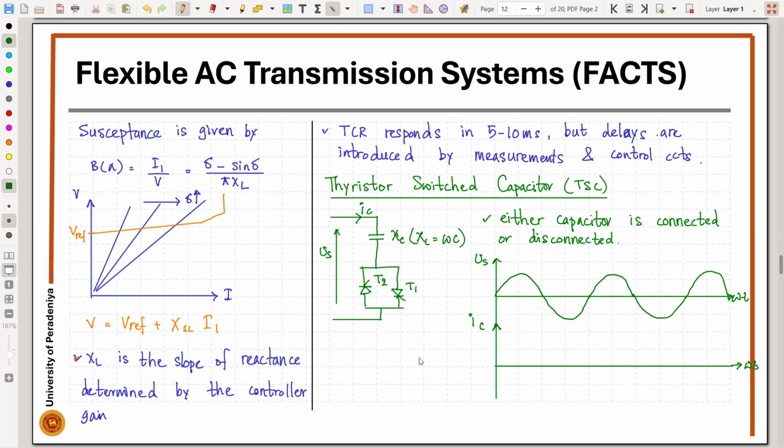usually when we want to turn on the thyristor, what we need to consider is the current flowing through the capacitor, because we cannot control the current through the capacitor. So we have to minimize the capacitor current flow. If the capacitor is not energized at the beginning, and if we just turn on when the voltage is at the peak, then there is a voltage drop and there will be a large current flowing through.